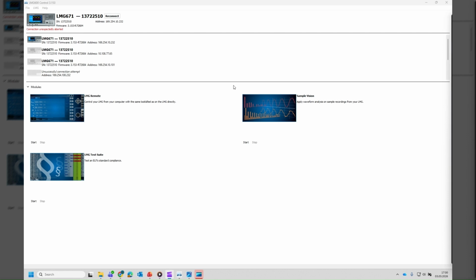The scope is used to analyze waveforms, to do measurements, FFT, mathematics, and much more, but the power analyzer is used for accuracy. So if you want to measure the power, the energy, the efficiency, the losses, the power analyzer is the right tool. And what you see here is the GUI of the power analyzer.